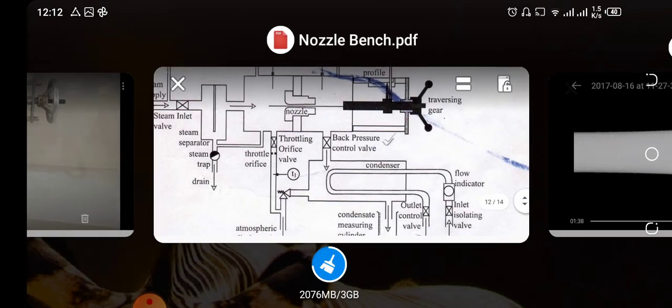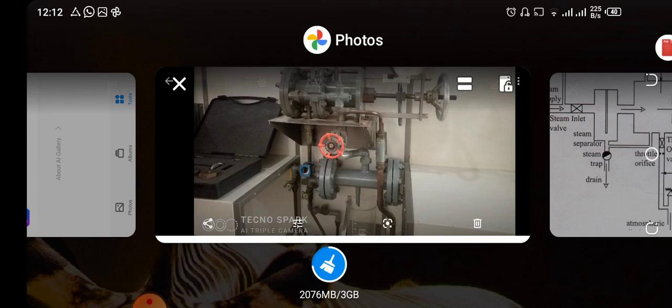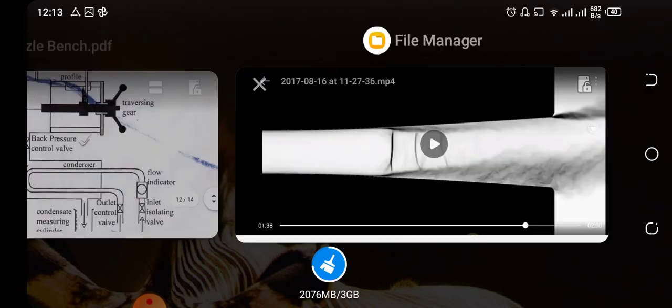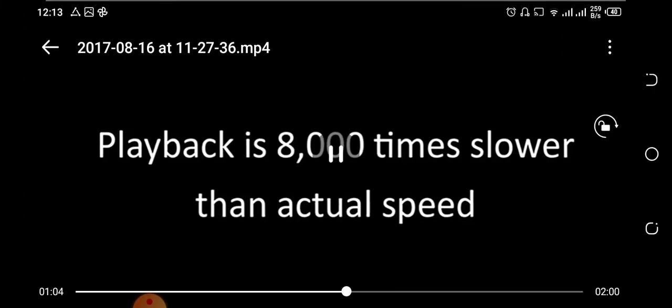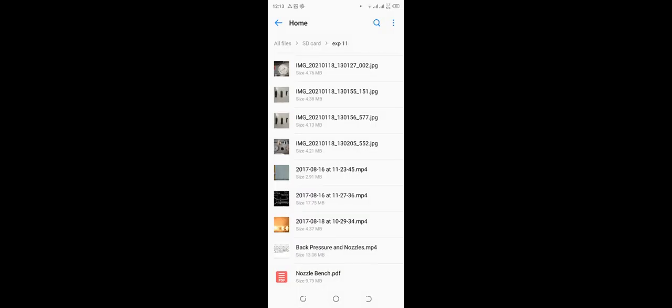After getting to the exit of the nozzle, you see that every propulsion system, whether it's a rocket going towards space, uses a converging-divergent nozzle, and we have lines of normal shock wave. Let me show you in this video. After passing out of the nozzle, this shock wave becomes oblique. Inside the enclosed path we have a straight line, somewhat curved, but when it goes to the open surface, it becomes a shock wave.